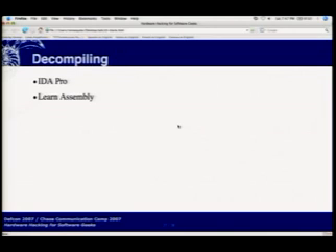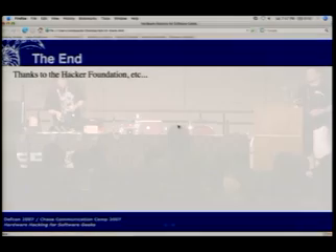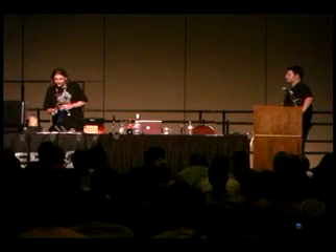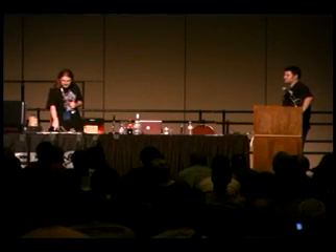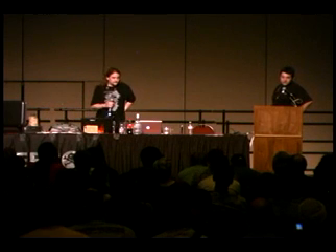It's 2 minutes. Okay. I actually have one up here. It's incredibly ghetto looking and got me all sorts of funny looks on the airplane over here, but that's the card reader, and I just desoldered the socket and then hooked up little metal bits to connect. They basically clip onto the chip itself. And then you can just use dd, you get a hex image out of that, and then throw it into IDA Pro.